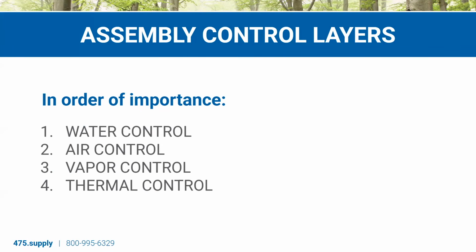A lot of projects have the option to have an exterior air barrier as their water resistant barrier, their house wrap, and or an interior air barrier that's normally doubling as their vapor control layer, a vapor variable membrane. Ideally, projects have both, but we'll talk through some climate zone specific considerations.